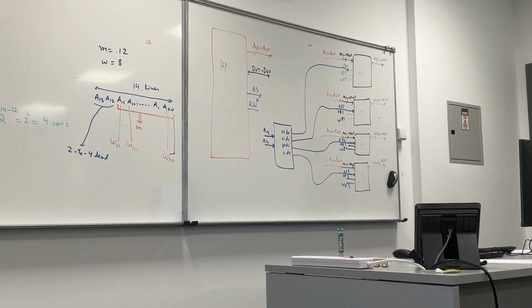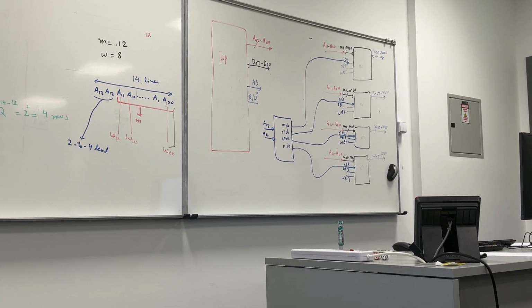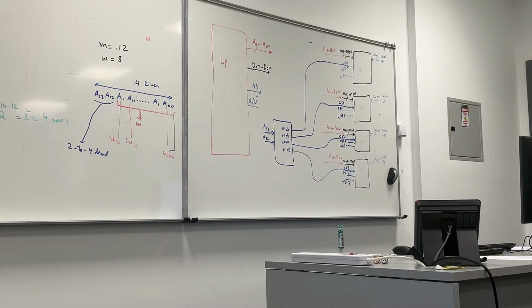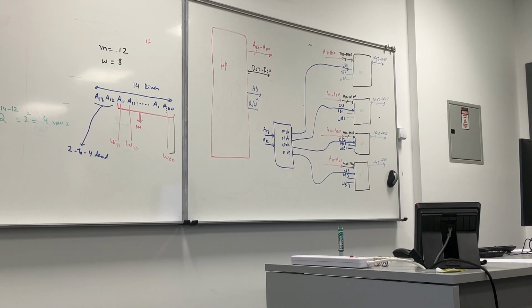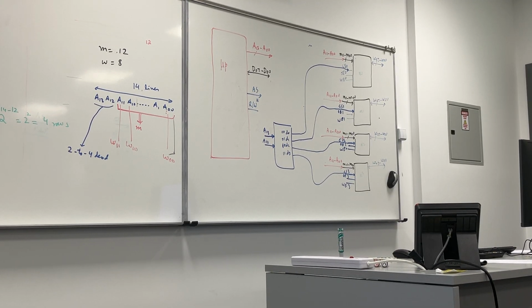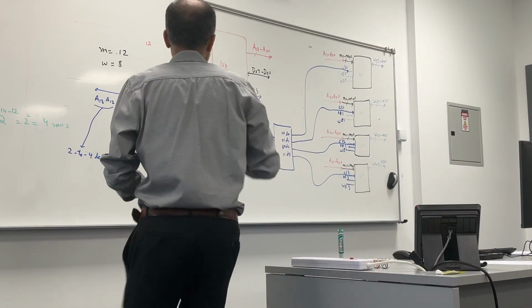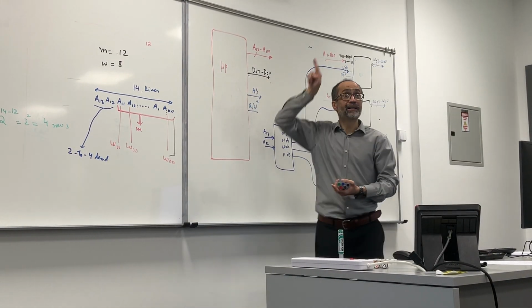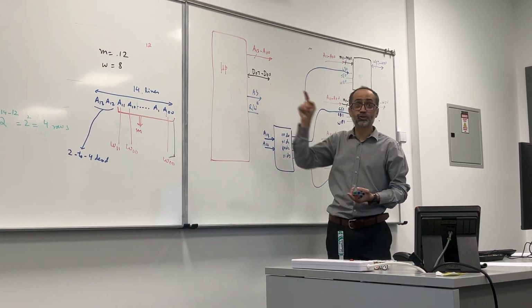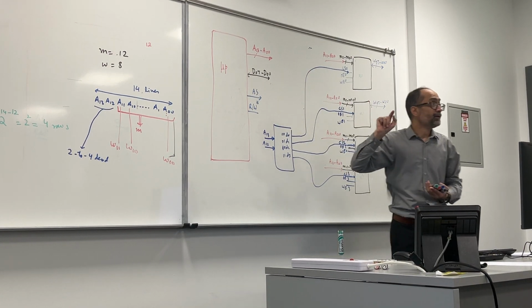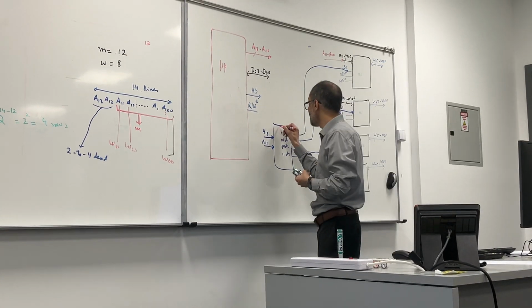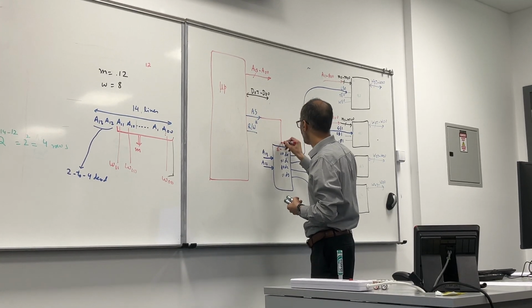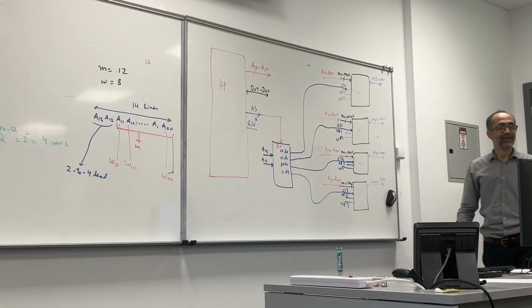Any question? Okay, now, when should this decoder be enabled? This decoder should be enabled when the microprocessor generates a valid address. So this address strobe will go where? To the enable of the decoder. So it means that now we have an enable signal in the decoder. So the address strobe will go here. Okay, now I will draw it.